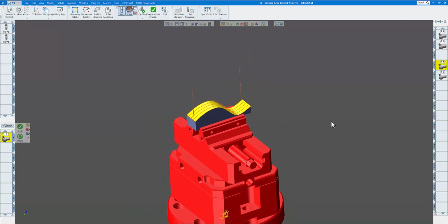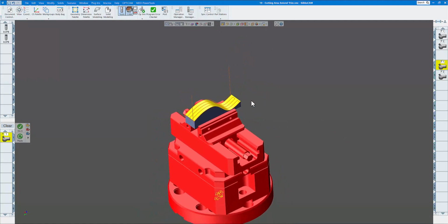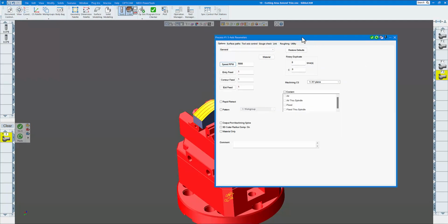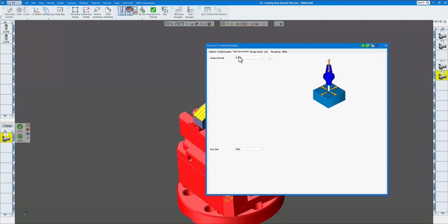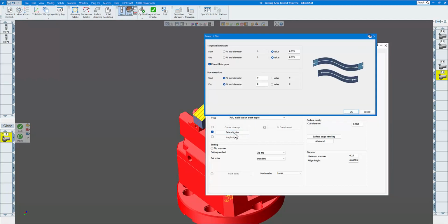So the last one, like I said before, sometimes you want to extend the toolpath a little bit to clean up any edges that might be a little bit past it. So let's open up number 5. So again, we're doing tool axis control, 3-axis, and surface paths. We're going down to extend trim. And again, I have a value here. I have a value of 375, so we'll just leave it there. That's fine.